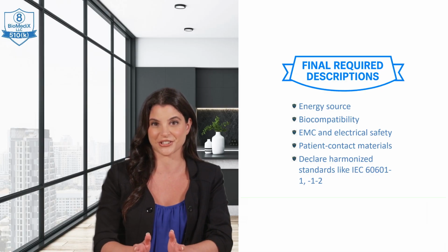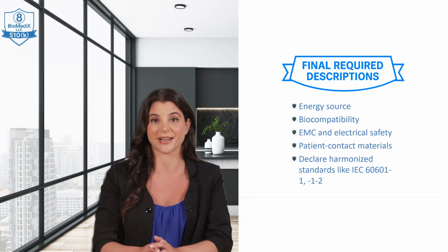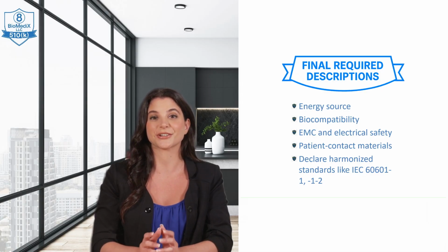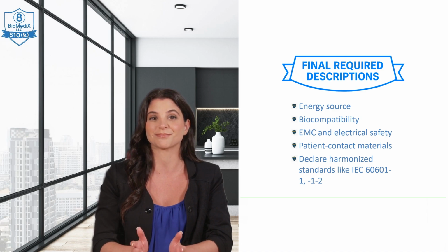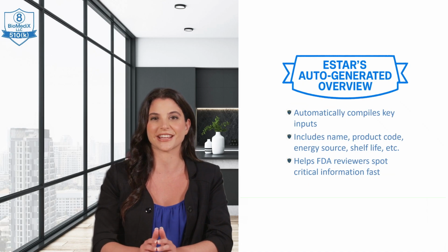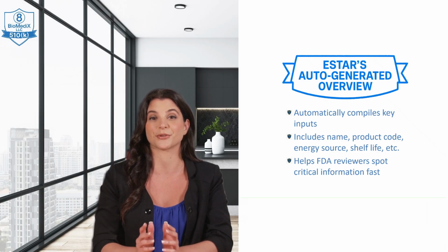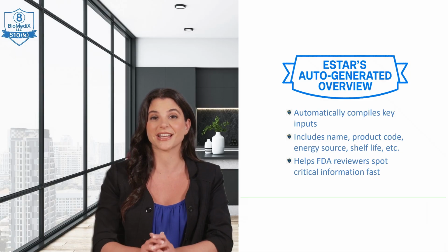Lastly, for other key characteristics, specify the energy source, environmental operating conditions, biocompatibility, electromagnetic compatibility, and electrical safety, and harmonized standards. Briefly mention materials that come into direct or indirect patient contact and confirm that biocompatibility has been addressed. For electrically powered devices, state compliance with standards such as IEC 60601-1 for electrical safety and IEC 60601-1-2 for EMC. Reference any recognized national or international consensus standards to which your device conforms, as this can significantly streamline review.